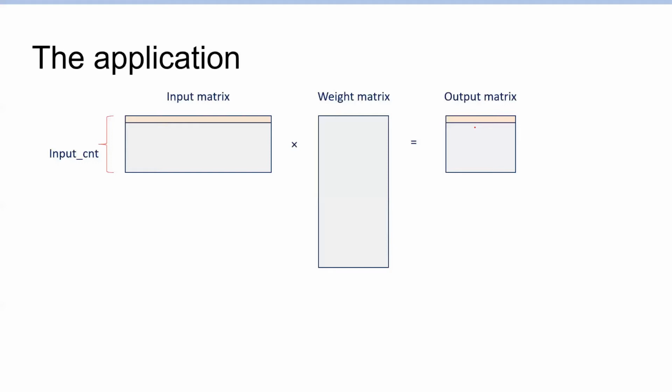What these two files do is pretty much the same thing we did for lab 1. At the bottom of it all, it's just matrix multiplication. It takes an input matrix, which will be initialized in software. The weight matrix will also be initialized in software, and the output matrix will be calculated inside the hardware by multiplying these two matrices together.